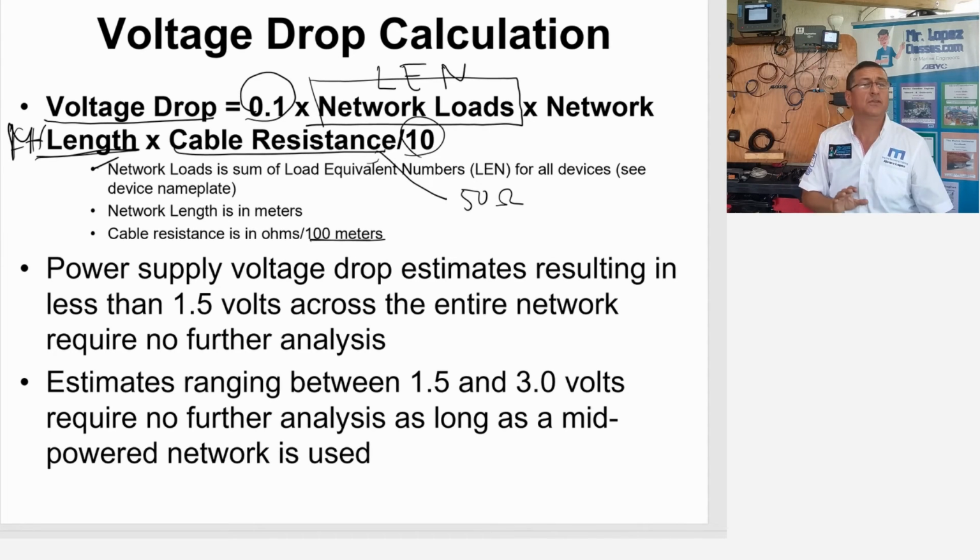When you have a code, you have three possibilities: too much equipment, too much voltage drop, too much drop distance, and or the distribution of the power is not appropriate. You need to divide the source of power: one in the middle, or two, one at each end, or three, one in the middle and two at the ends, in order to stabilize the voltage on the trunk. This is my recommendation.